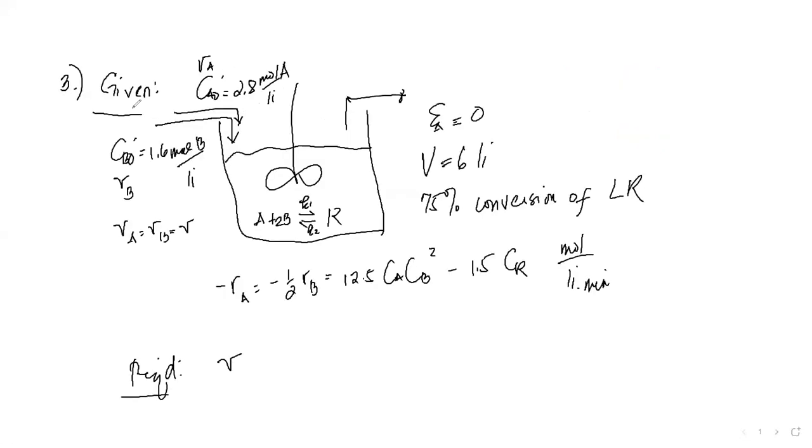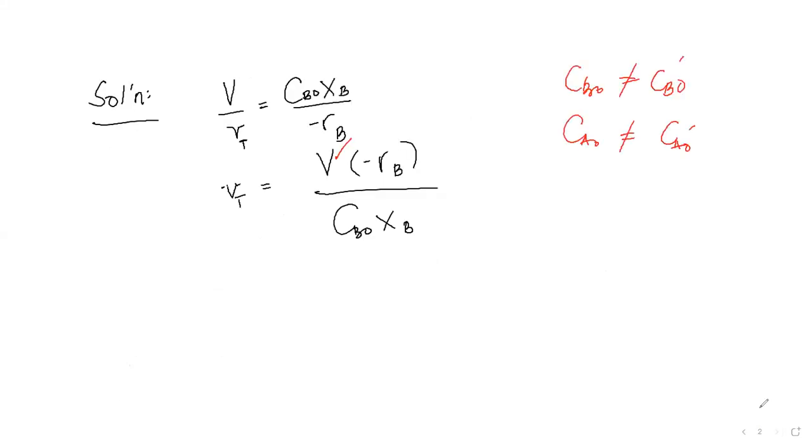You see there are primes here because these concentrations are based on the concentrations of these separate streams. But when we already determine whatever it is that is to be determined in a problem that has separate streams, you have to account for the real concentration of A and B in mixture form already, not in separate streams. These are the separate stream concentrations, and we want the mixture of these two as a whole already if these two separate streams are already mixed.